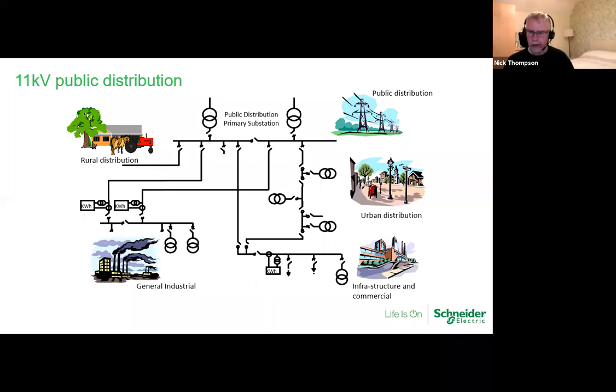And we've got our primary distribution board, which is this large switchboard here, which will have multiple feeders at different current ratings, with typically going to be 2000 amp incomers with a 2000 amp bus section. And then we've got a ring showing there, and this will be a co-ownership switchboard. And then they've got their own feeders there.